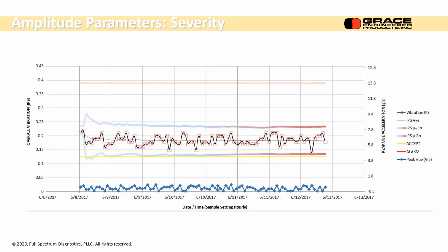And when we're looking at amplitudes, here's something I brought up on Tuesday. I'll do a little more of this next Tuesday, but this is some sampling and some statistics on just 4 days of data from a power plant. So this was a big vertical pump. I have a bunch of statistics in here, but I'm looking for an alarm criteria. And what I have is a value that's changing the more data I get. As I'm taking data, I'm adding to my statistical population. And once I get out here 4 days later, my alarm criteria has gone down and squeezed in there.